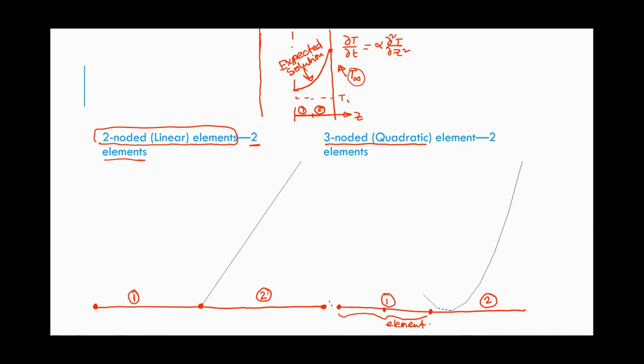And so now let's do the computation here, and let's see how it goes with time. So with time, temperature increases. If I stop for a second, then you can see the expected temperature profile makes sense, because the entire region is divided into two elements. For every element, I have the nodal temperatures that we calculate, and every point in between we interpolate.